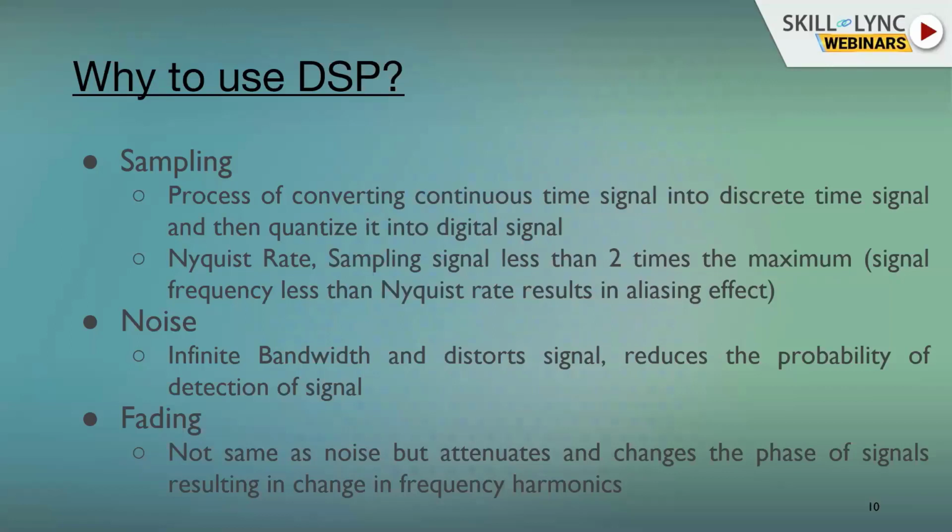Okay. So if you are sampling at a higher rate, for example, to maintain the quality, is it going to take a toll on the performance? Yes, maybe yes or no. It could be, because it depends upon the type of application you're looking at. For example, with a speech signal, you may not need to oversample at higher rates, whereas in wireless, you may need to sample at a higher rate to reduce the effects of channel impairments and noise signals.